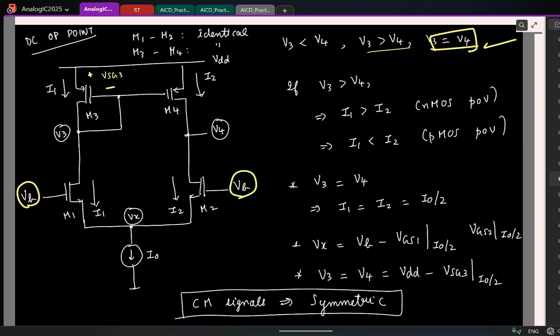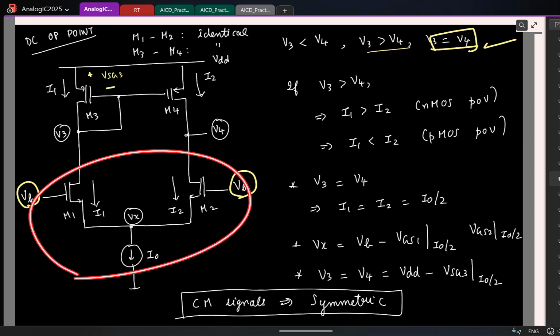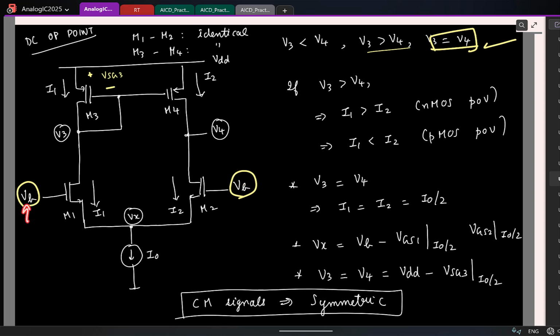Again, this is a common point of confusion, making it a nice question for interviews. A lot of times students might think that, hey, I am increasing the gate voltage, so the current will increase. That's not the case. That's why I want you to understand what kind of biasing we are doing for transistors. Here particularly we are biasing with a constant current. So it doesn't matter if you change the gate voltage, the source voltage will adjust automatically to keep the current constant.